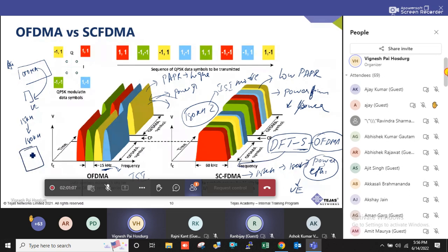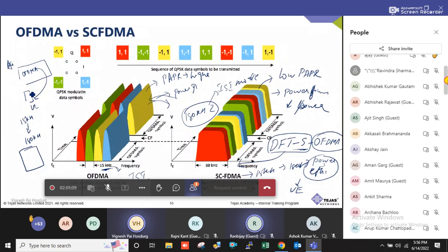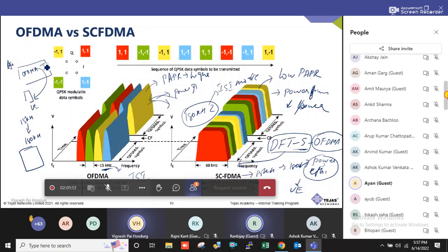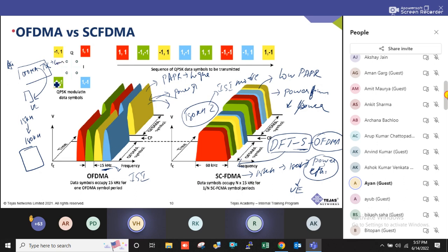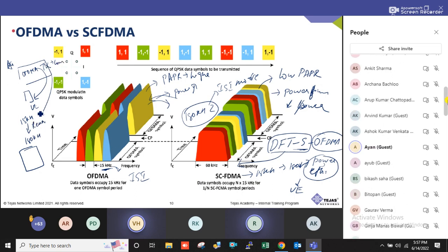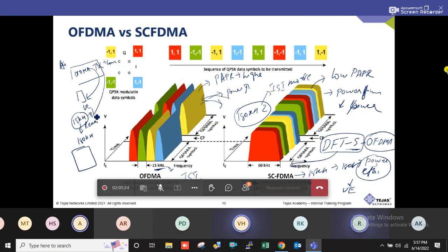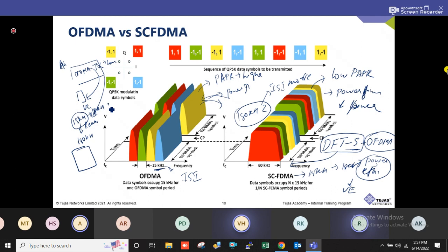Everything is predefined. So the UE understands this. That means in the OFDMA technique, the transmitter is complex, but the receiver is simple, because the receiver has to just receive this data at this particular, let's say not 15 kilohertz, maybe around 180 kilohertz. This is clearly outlined to the UE according to the standards or specifications.